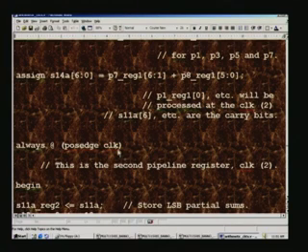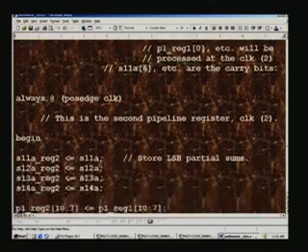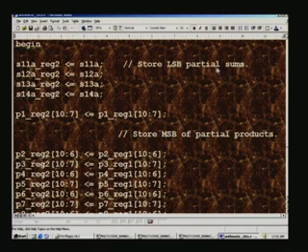So, with the arrival of the next positive edge of the clock, this is the second pipeline register, clock 2, what we do here is store LSB partial sums. We have already evaluated the LSB partial sum, and we need to store it here and put it in a pipeline register, and this is how it should propagate. Because we have not yet used the result, and we will use it only on a subsequent clock pulse, till then you have to keep on propagating it, and all this would mean extra chip area naturally, but the goal is to speed up the entire operation.